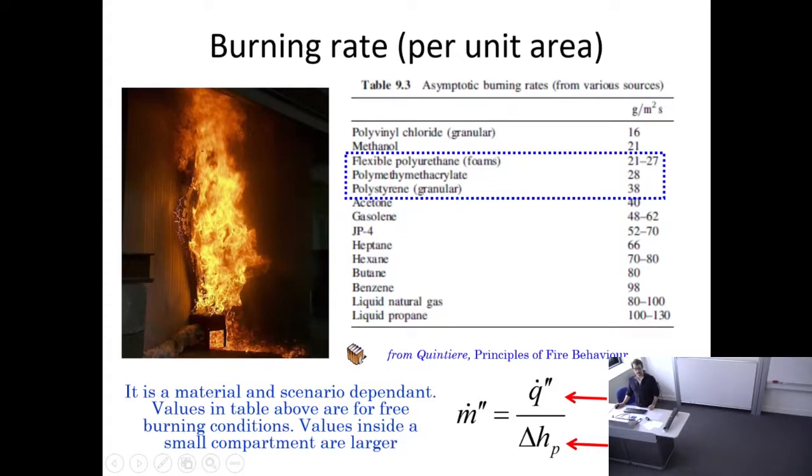Okay, which is the amount of fuel. Because taking into account polyethylene foam, it's mostly air. It's literally 95% air. There is very little fuel in it. So although it ignites really quickly, there is very little fuel that actually can be released. But then polyethylene foam itself is not the fire that you worry about, it's that the polyethylene foam will actually start to ignite other things around, and they will drive the fire in a different way.